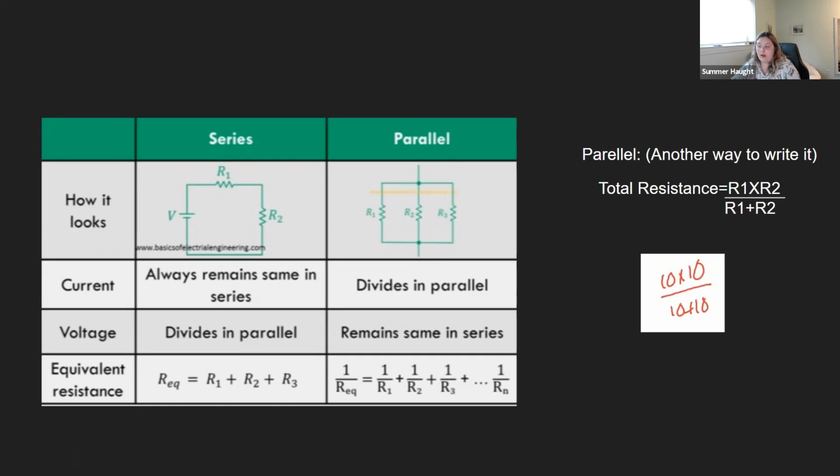These are important. Basically what this week does is it shows us that in real world situations, we very rarely have just a series circuit or just a parallel circuit. Typically we have both. And we are basically going to learn how to calculate total resistance or equivalent resistance, total current, and total voltage, given situations where we have a combination circuit. And a combination circuit is just one that is both a series and a parallel circuit. If that doesn't make sense, it will in a minute.